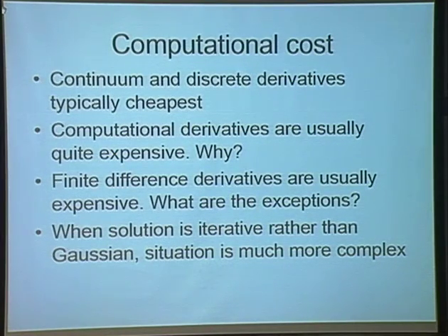Yeah, that is, nuclear reactors are not thin wall structures. Now, why is that important for Gaussian elimination? Does anybody see a connection? When you have a plate, even if you use solid elements, the bandwidth tends to be small because it's in the plane.